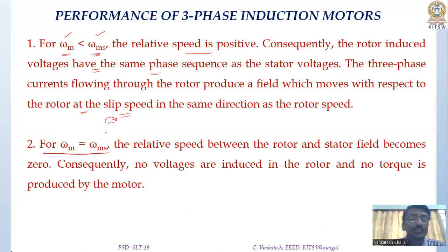to the synchronous speed of the stator field, then the slip speed becomes zero. When the slip speed becomes zero, both the rotor and the flux are rotating at the same speed, and hence there will be no torque produced, and hence the motor stalls or stops.